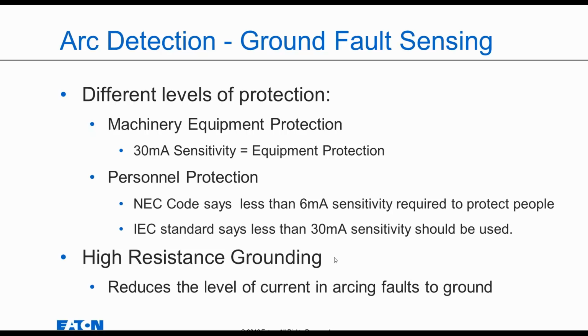High resistance grounding is getting a lot of good publicity too, because with high resistance grounding you can limit the level of the arcing current and lower the detection level from the equipment. And this is used, I know, a lot more in the system design.